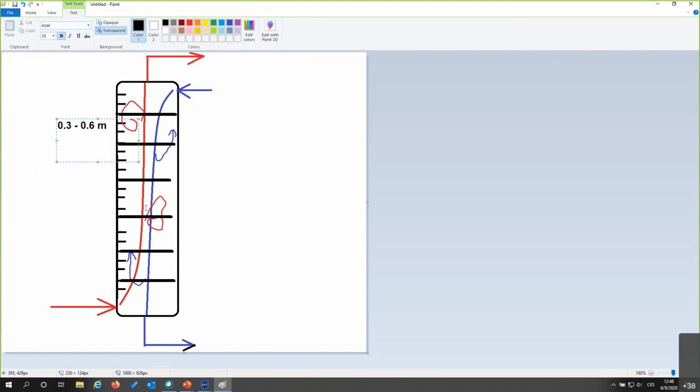Tanya is asking what I said is a typical increment height for an amine absorber. This is in line with the general recommendation. So I would say between 0.3 and 0.6. Again, if you want to be more conservative, you would stay on the higher values, so closer to 0.6. If you want to be less conservative, you can go around 0.3. Or if you want to do this little study I just showed you yourself, and maybe be even less conservative, you definitely can use the scenario tool and a random parametric study to see it yourself.